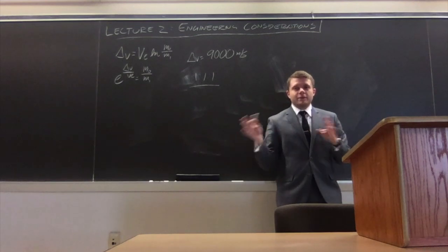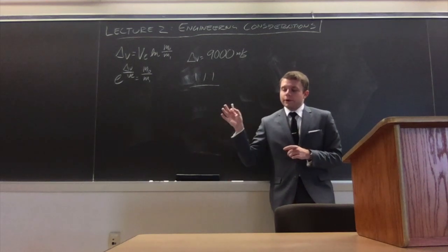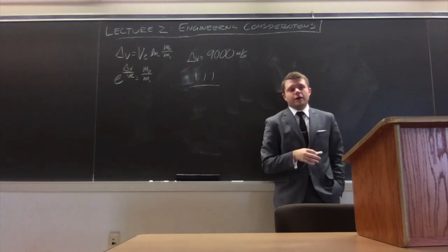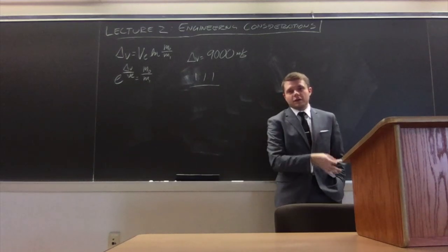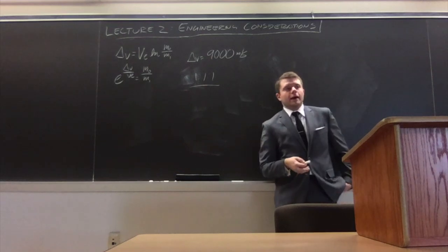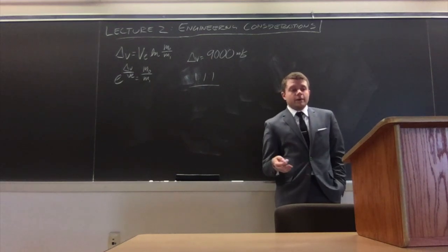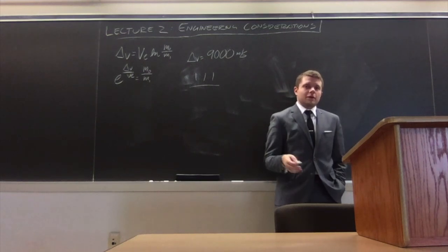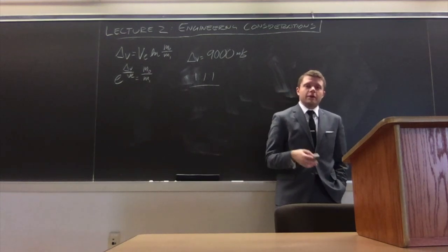That's generally true. You have to make engineering considerations for that as well. But as an approximation, we can generally use a nice round number between the sea level specific impulse in atmosphere and the vacuum specific impulse. There are calculations that rely on the vacuum specific impulse, but that's a special case and a special setup, and I'll get into that at the very end of this lecture.